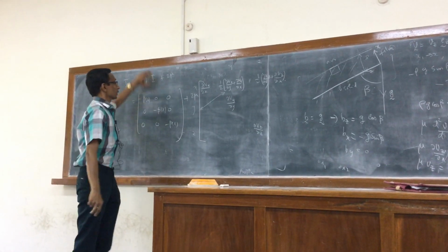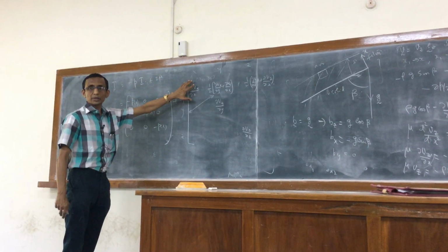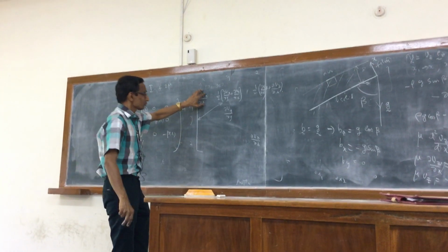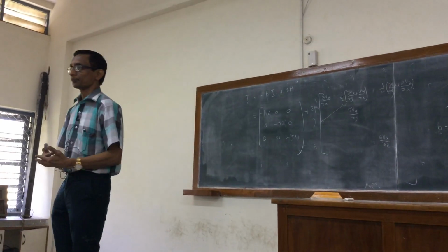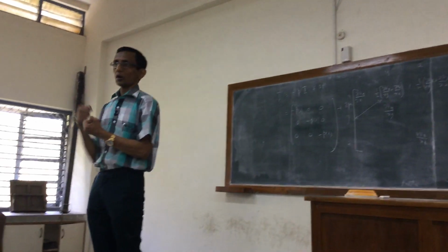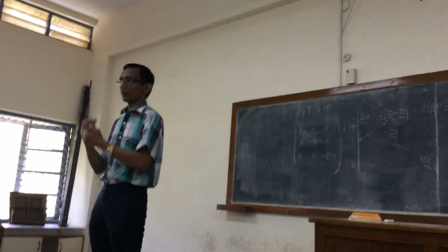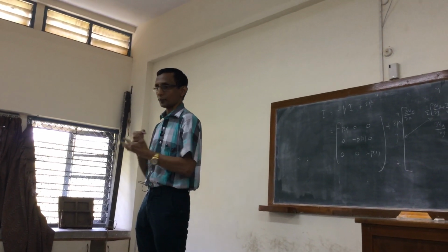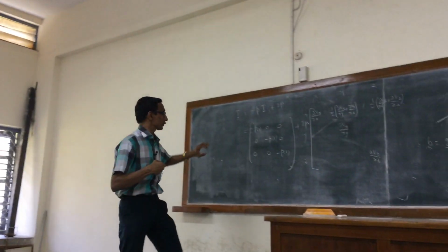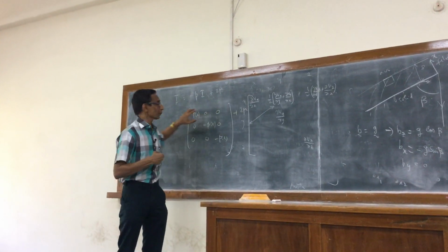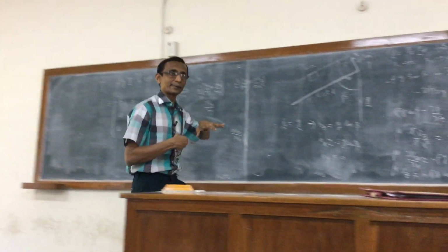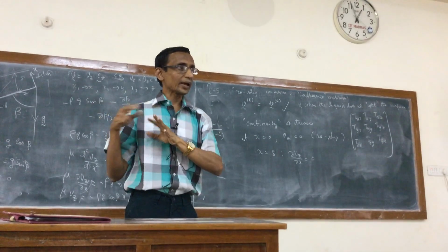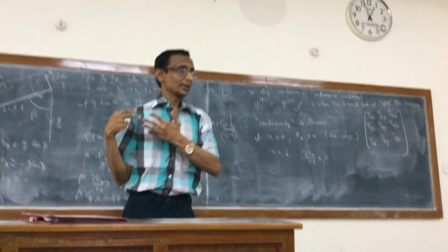Usually the shear stress is, so the interpretation is that these will also be normal stresses, because they are also diagonal. D11 means the normal is in direction e1, and we are looking at the component in the e1 direction, so that's also a normal stress. So all the diagonal elements of the stress are split into two parts. One part is coming from the pressure, the hydrostatic part. The other part is coming from D itself. Right? So the off-diagonal elements are what are referred to as shear stresses.